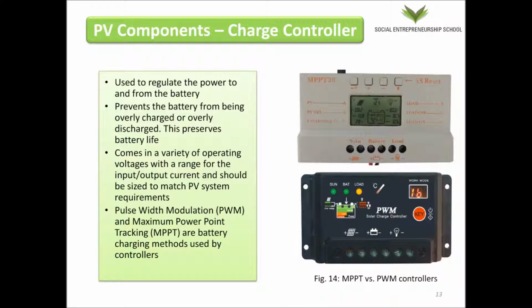Charge controllers should be matched to the electrochemistry of the battery. They should be sized such that they can accept the maximum current and the maximum voltage of the PV array, and also output the voltage of the battery.